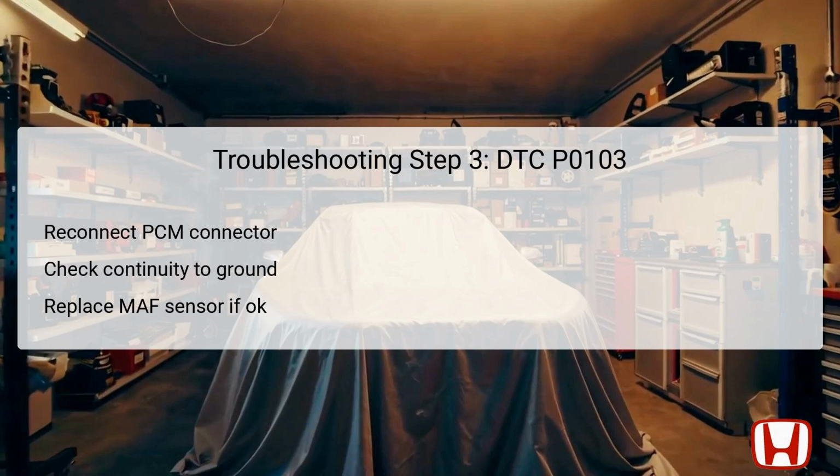In this situation, the MAF sensor or IAT sensor would need to be replaced, as it is likely contributing to the high voltage condition. If continuity is absent, further investigation is needed, which may involve consulting authorized service information related to the DTCs or symptoms being addressed. Alternatively, substituting a known good PCM could help determine if the existing one is at fault.